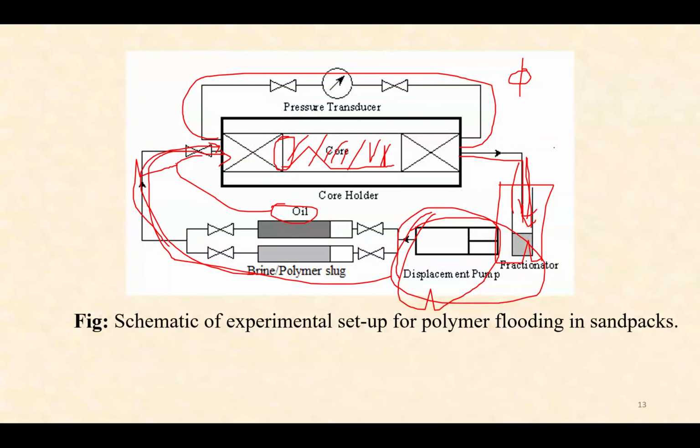during water flooding. Sometimes your water cut reaches 95%, and in this condition it is really difficult to continue production, because very little oil will be produced, and treatment of the huge amount of produced water is very difficult. So your process will not be economically viable. So you have to think of another enhanced oil recovery method.